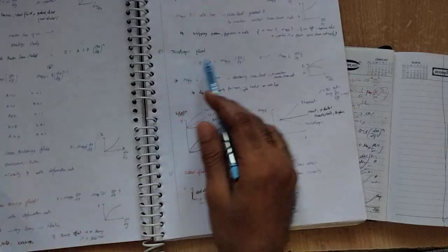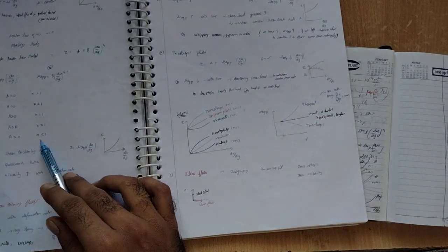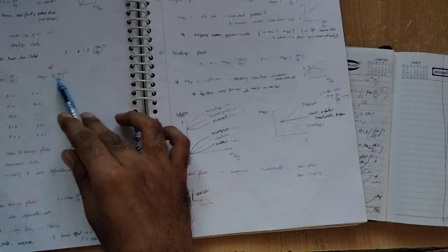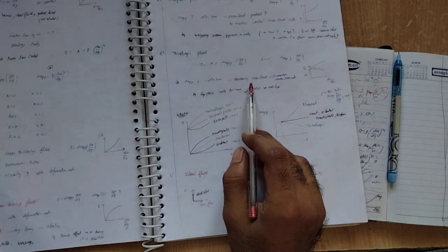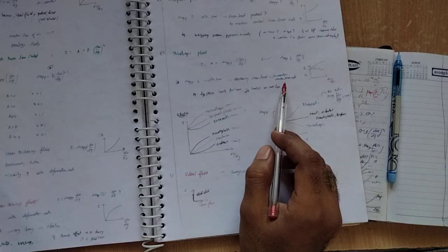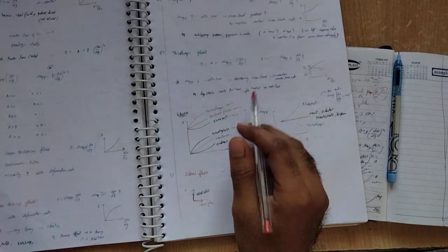So next one, thixotropic. You can see whenever du/dy increases, mu apparent decreases because n is less than 1, so this entire equation becomes negative. So mu apparent decreases with time, with a decrease of shear load to maintain a constant strain rate. An example is lipstick. When you apply it, it is first hard.